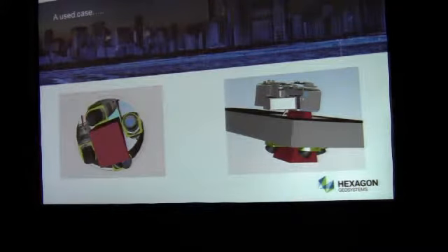One of the things that we hear a lot is, of course, 3D city modeling. If that's a use case going forward, and you'd like to have oblique images and LiDAR images, to get through the trees, maybe one of the things, and that's a concept study that you were working on, is to combine a LiDAR with an imager. In this case, it's two different technologies. It's an oblique camera, so you don't need the nadir view. You can replace that with a relatively narrow field of view for a LiDAR, and you have one system that fits in one camera hole. Oblique data is mostly flown with small aircraft, Cessna 206 or so forth, so you don't have the chance to have a two-hole system.